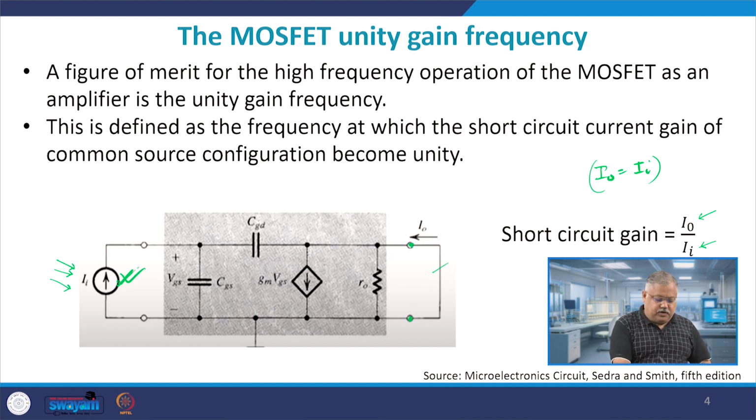As you change the frequency of the input signal, the gain starts to vary, right, and the gain is not constant, it varies with frequency. You can understand why, because we have discussed just now that as the frequency changes, some of the capacitors become short, and some of the capacitors become open, and inductors become short, because if you remember, I was discussing with you that an inductor is equal to j omega L.